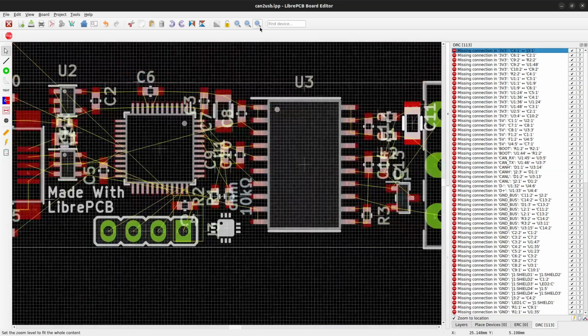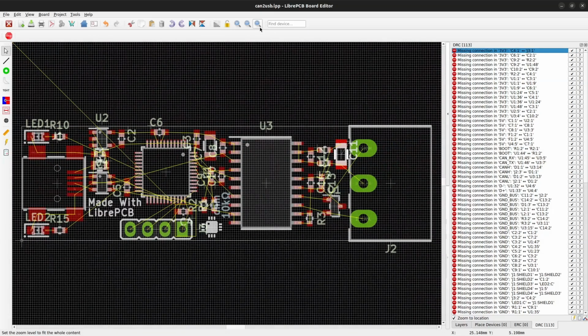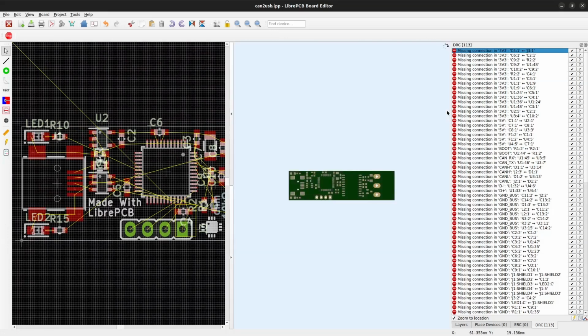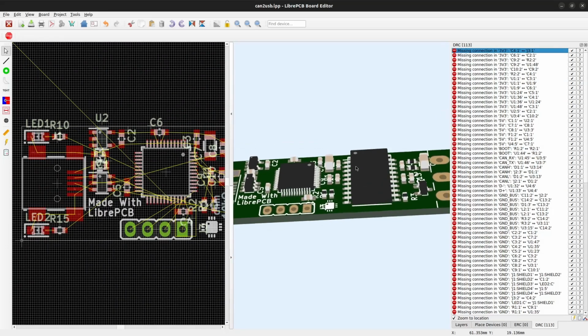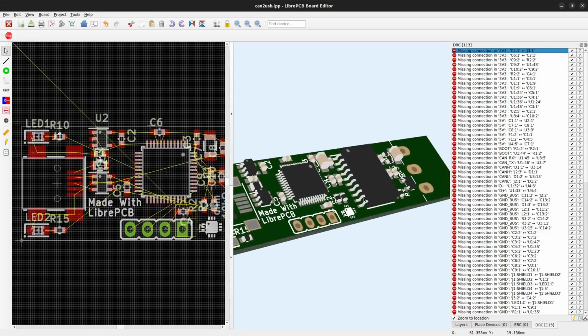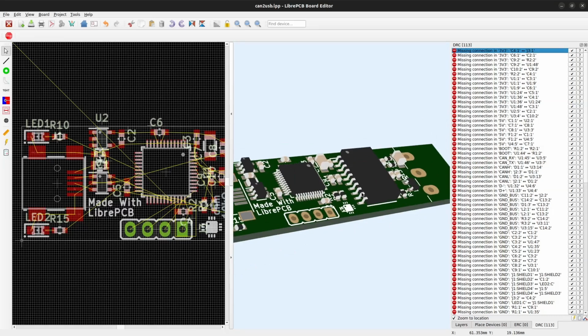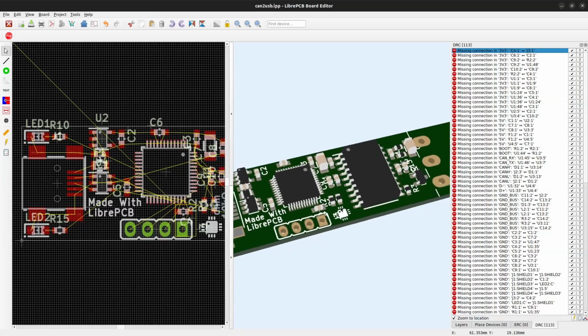The second thing which you should do is to open the 3D viewer. Here you'll get a good impression how the final PCB will look, and many potential issues would be visible here. For example, is there enough space around holes to insert screws? Are all pads accessible by a soldering iron? Is there enough space around connectors for their mating part plus cable?